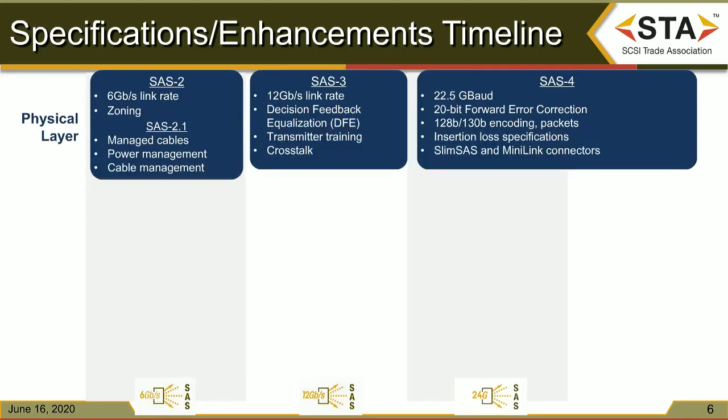So with a basic understanding of SAS, we can take a little bit deeper look into the makeup of SAS. And we find this pretty interesting. The SAS specification is broken into layers, which are developed and published independently. The physical layer, denoted by SAS, specifies the functional requirements for the serial attached SCSI physical interconnect. So this on a device is typically the PHY layer and a good portion of the wrapper, depending on how it's implemented. It's important to note that all SAS physical layers are definitely compatible with the Serial ATA physical interconnect specification.